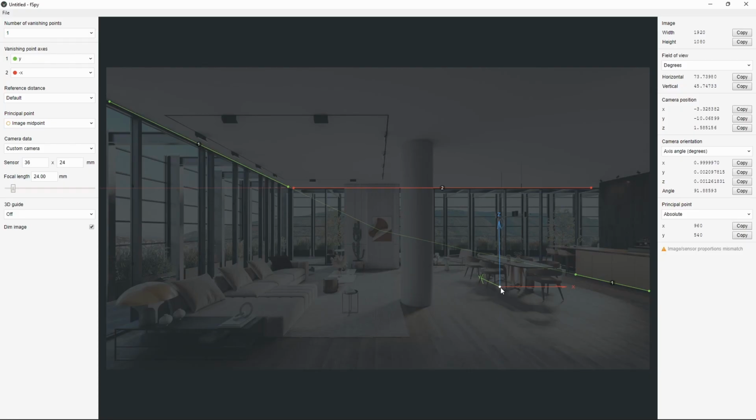We can validate our perspective now by dragging this origin and matching it against various areas of the image. As you can see, apparently we have some issues with the Z-axis. It doesn't align well with the underlying picture, but kind of bends towards the middle of the image. This problem is very common with images that have less than 3 vanishing points. Generally speaking, axes without vanishing points are troublesome. Not always, but quite often. fSpy simply doesn't have sufficient information to do its job in such cases.